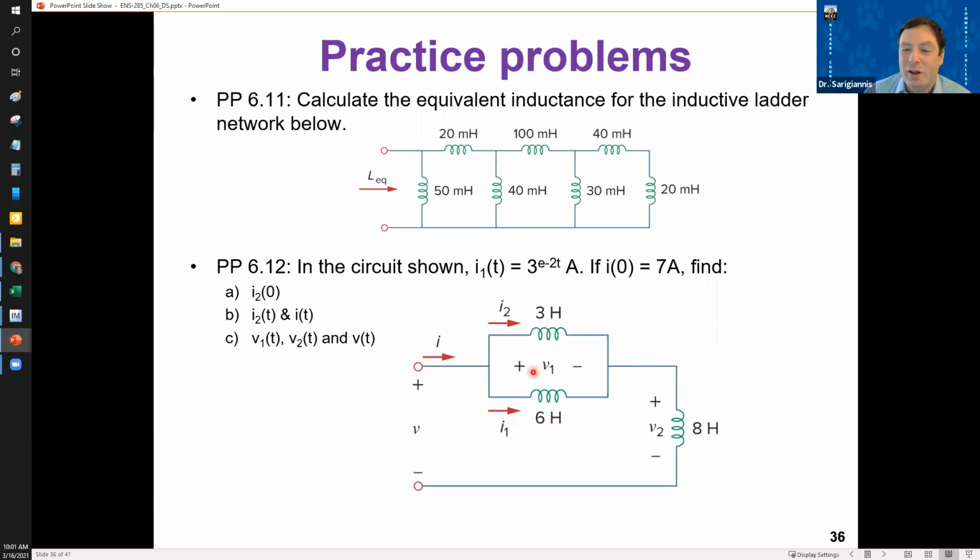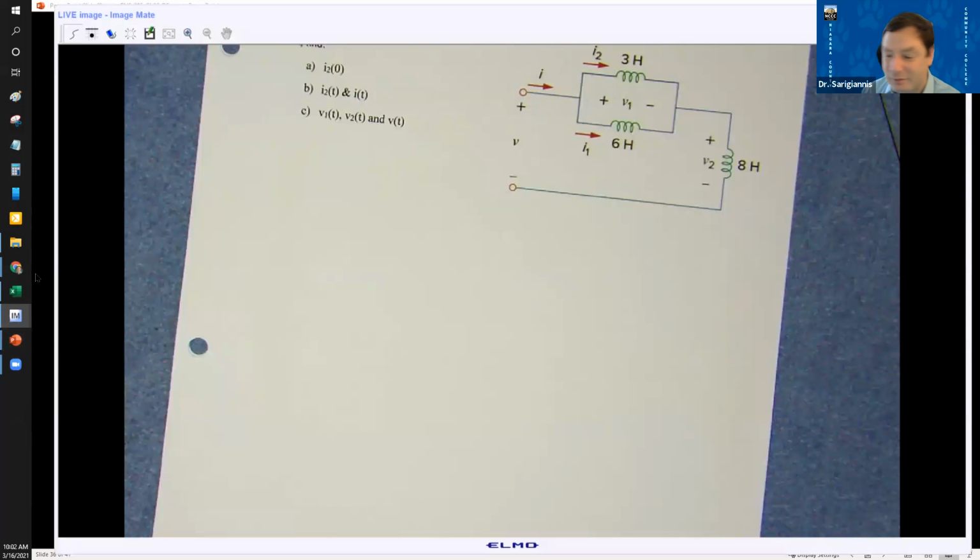Now notice again, looking at this circuit, you shouldn't have to be given this. You should recognize that the voltage drop over these two things is the same. You can't have a higher potential over one than the other, because it's going to even out. Whatever one's the limiting one is going to result in increasing the potential here. So you've got this potential drop, and then you've got this potential drop here, V2. All right, so let's look at this thing and figure it out.